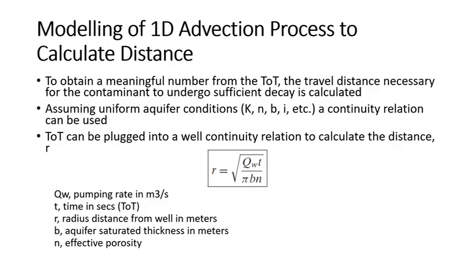Once we have that time of travel, we plug it into the well continuity relation to get the distance that is necessary for that time of travel to occur.